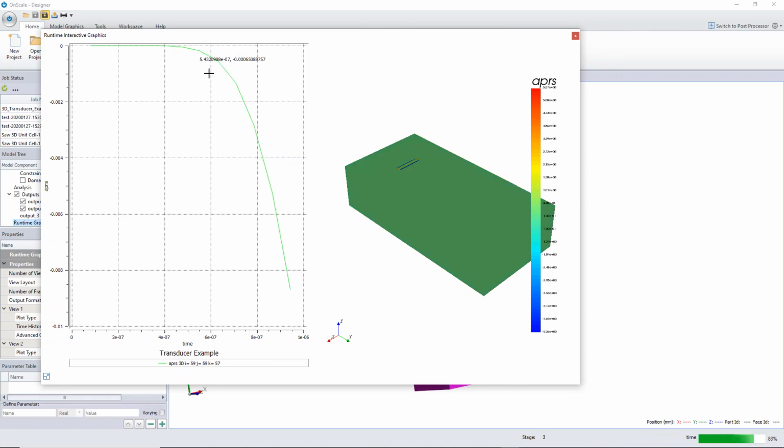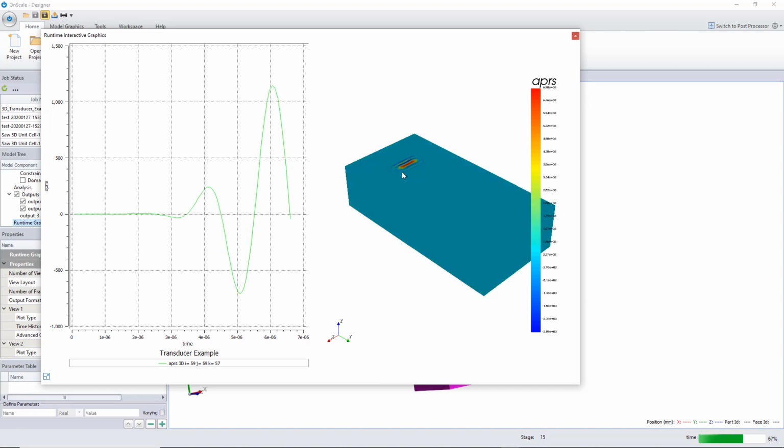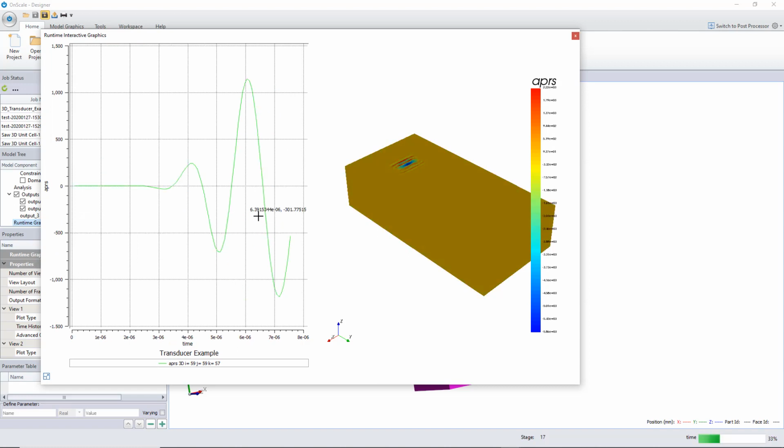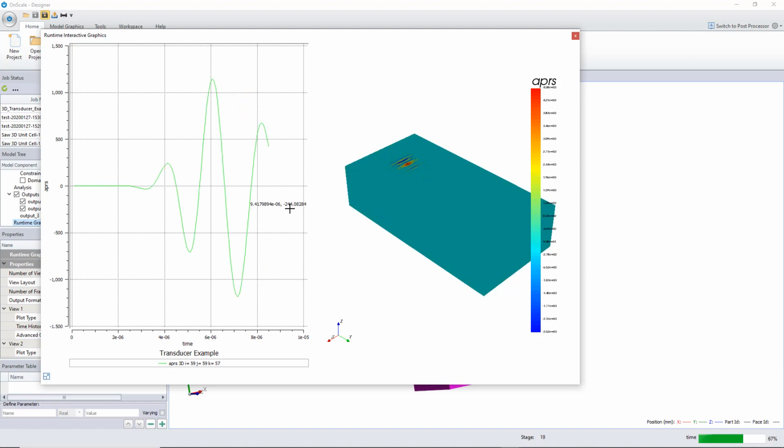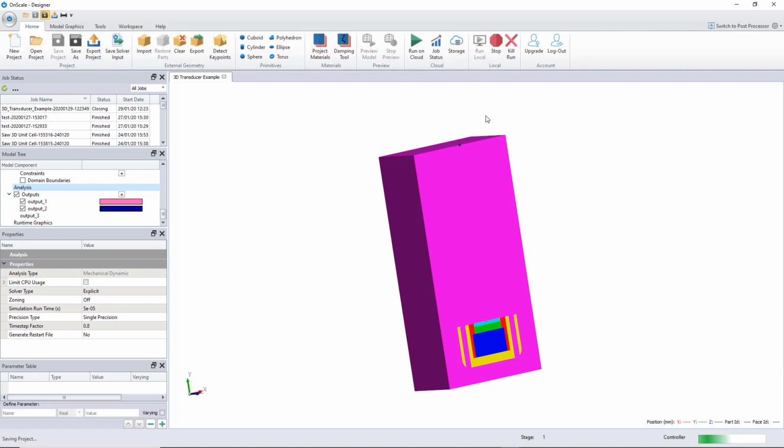So as you see, my mesh size seems okay. So it's running and launching simulation. Here, the analysis seems to be a bit short. It's only calculating a part of the input, so I may have to increase the simulation time. Let's increase that to 5 times, and let's run that again.